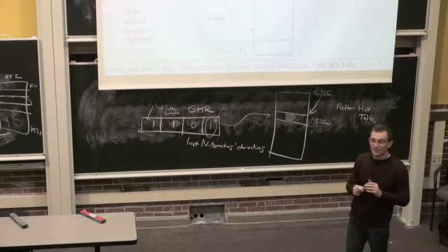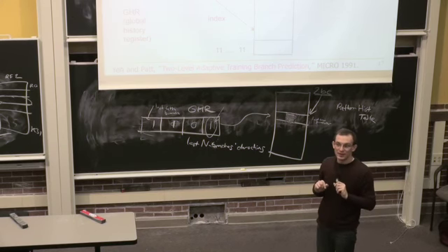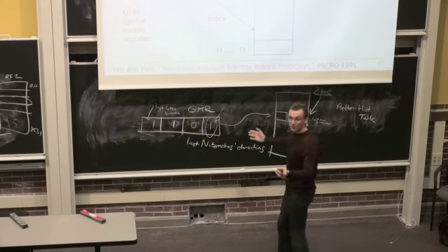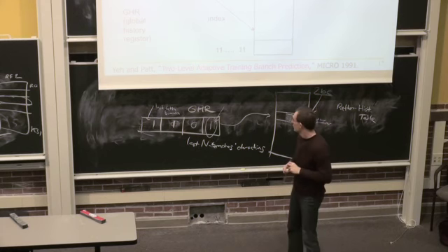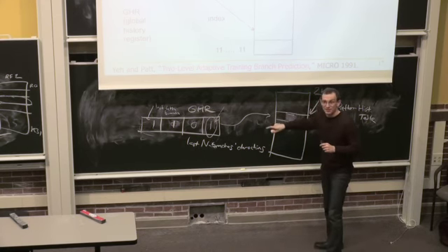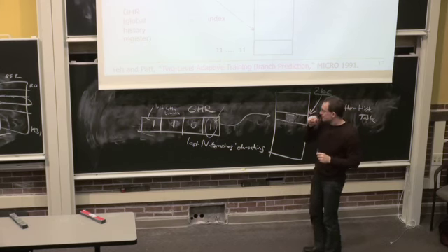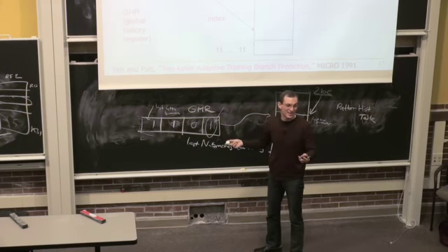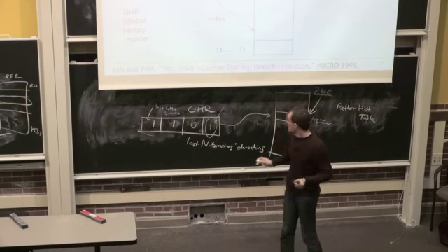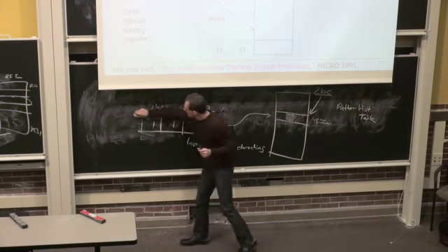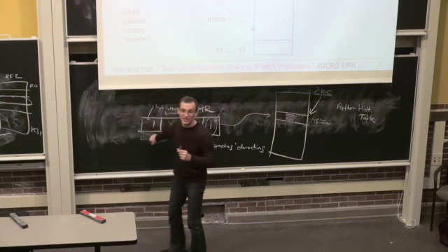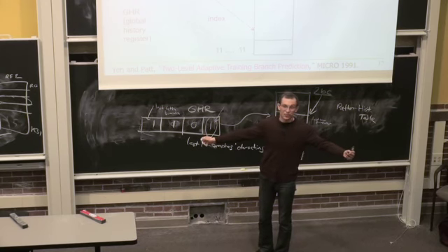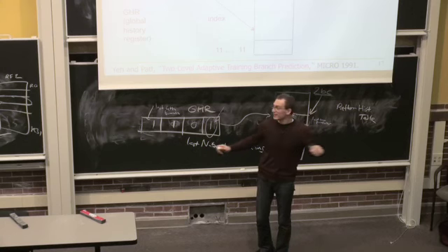Usually the way it's done in industry is you have a set of workloads, and you design your pipeline, and basically you have a timing simulator. You could just simulate the branch predictor, actually, and run your workloads for different history lengths and figure out the prediction accuracy. Normally, as you increase this length, your prediction accuracy increases because you're capturing more correlation into the past. But there's one downside, of course.